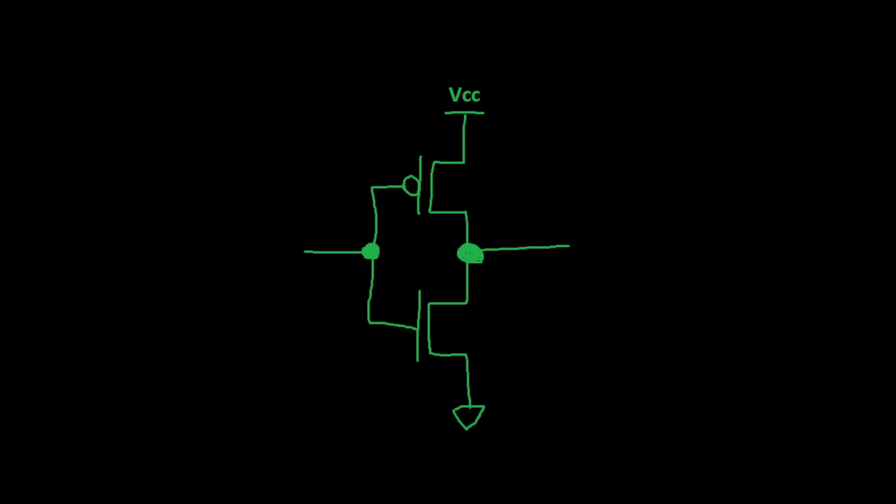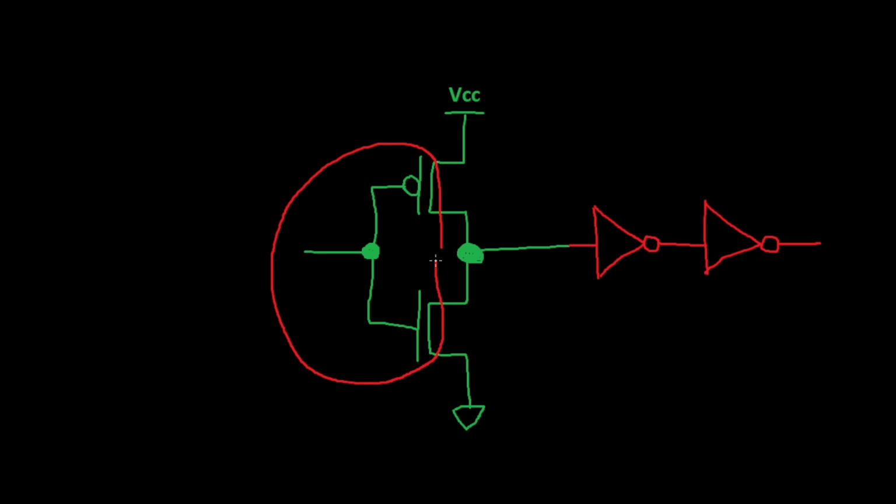In addition to having this simple CMOS circuit inside of an inverter, quite often, this circuit will be repeated. Rather than drawing it again, I'm just going to draw the inverter symbol here. But you can just imagine that that same circuit is repeated 2 more times. This is what's called a buffered inverter. There may be more than just 3 stages. It will depend on the device, how it was designed, and its application. However, the operation of it is pretty much the same regardless of how many stages there are. And specifically today, we're going to be looking at the input, so we're really worried about what's going on this side, not so much what's going on past this.